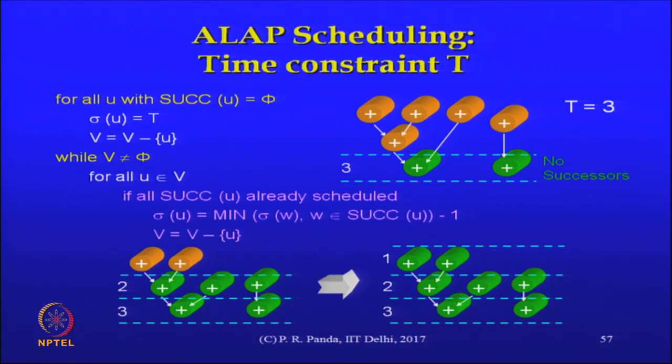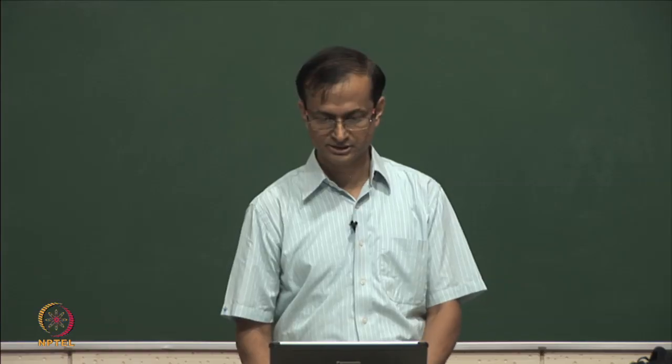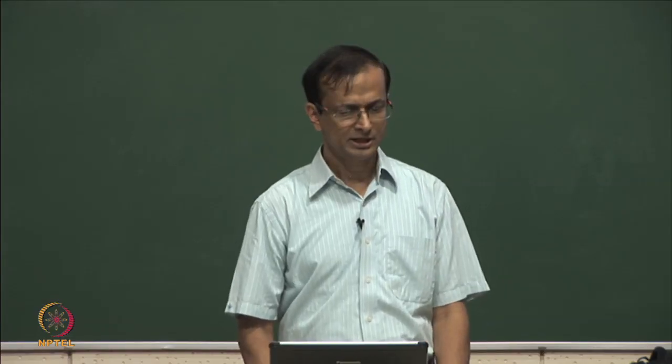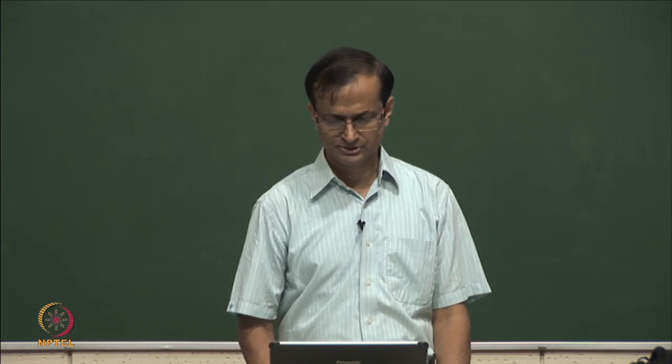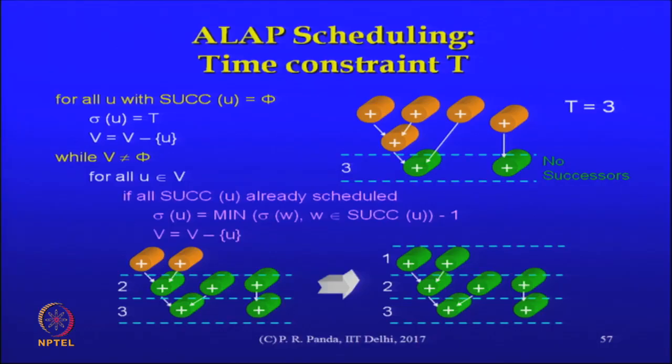Both of these are relatively straightforward. These are not difficult, right. This is the extreme where the assumption was that there is no resource constraint. So, obviously, this is just an ideal schedule. It does tell us something though. Some valuable information could be inferred by just doing an infinite resource scheduling like the ASAP and ALAP, even in the context where resources might be constrained in some way.